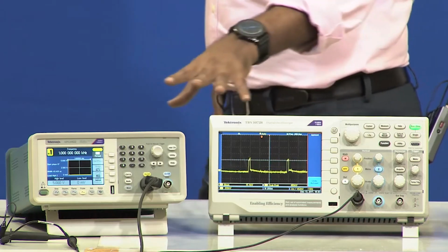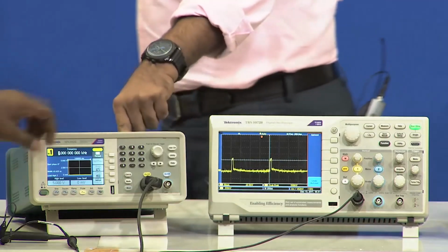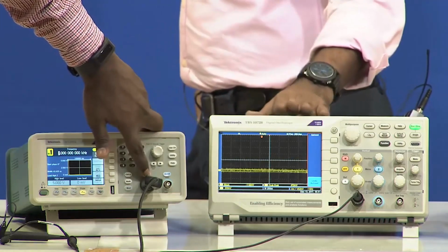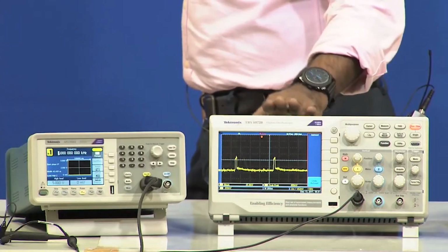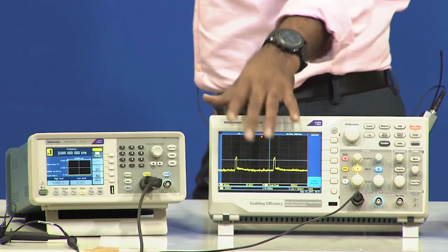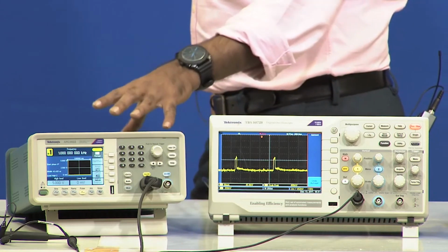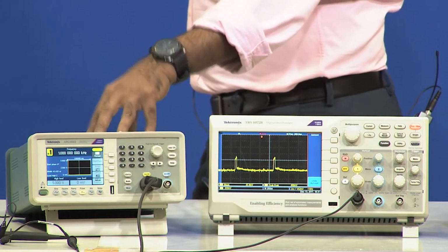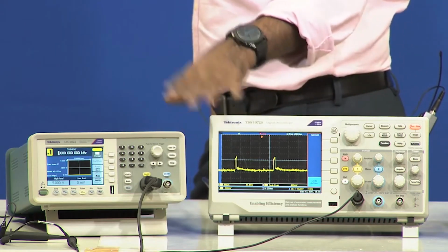Now, we can also stop the signal. The run and stop button is there, and here I think run and stop button is here. So, you see you have now captured the signal. This capturing of signal you can save using your USB drive, your USB port, right. So, now we can connect it to the function generator, you can connect your oscilloscope and then you can save the data in the USB drive.